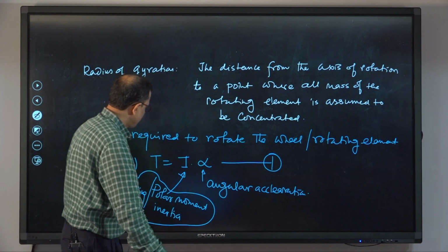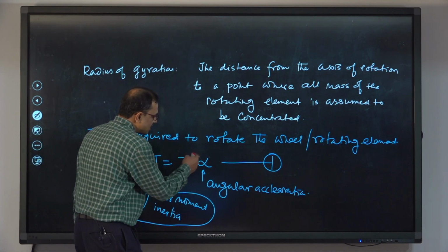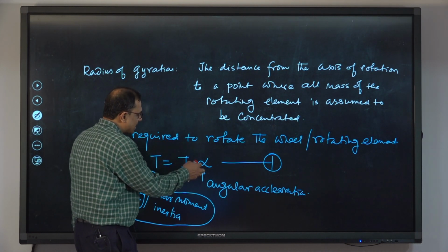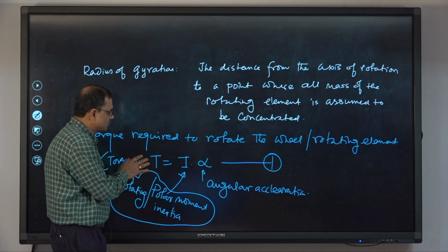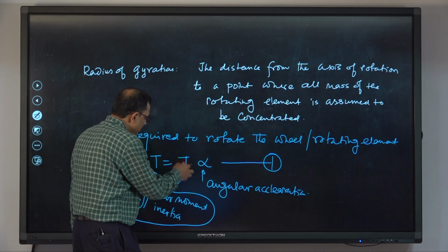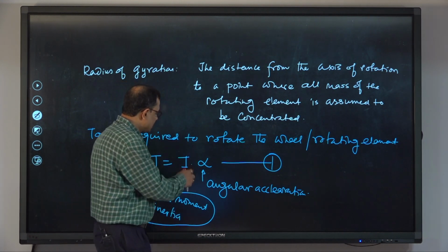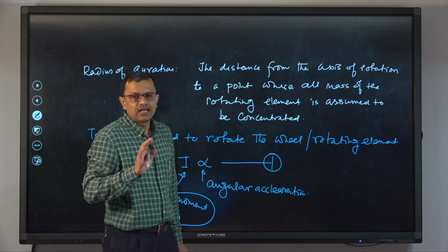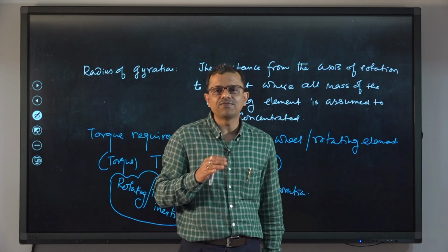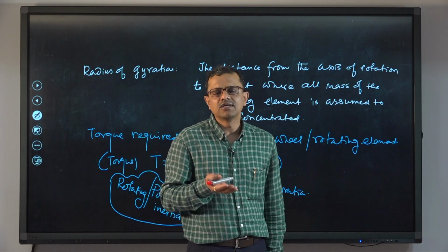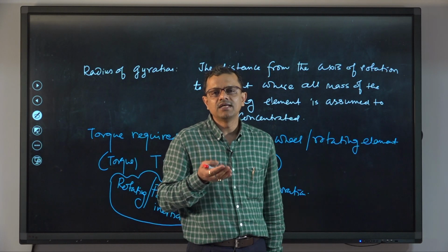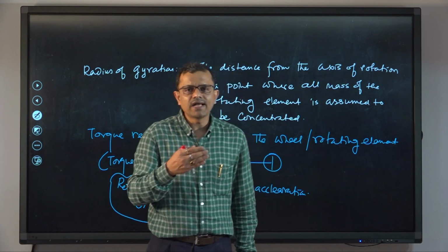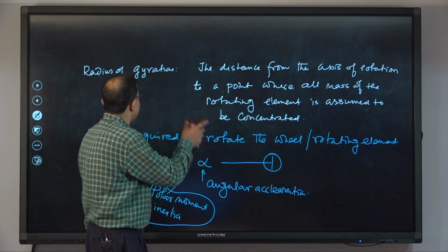Let me tell you once again, from the equation itself I can understand that angular acceleration is very important for the wheel. For a given amount of torque, if torque is fixed, then if I halve the polar moment of inertia, we can double the angular acceleration for the given torque, right. So, if we use lightweight ceramic material for the construction of the turbine wheel, perhaps the polar moment of inertia, the rotating inertia, can be reduced, which in turn will ensure some improvement of the turbine wheel in the context of turbo lag.